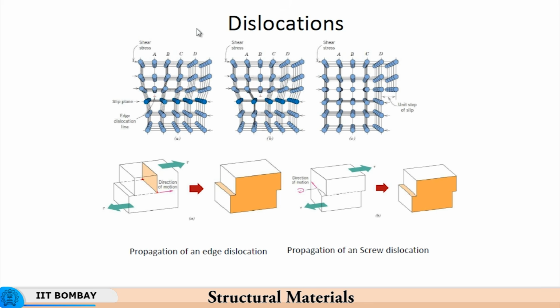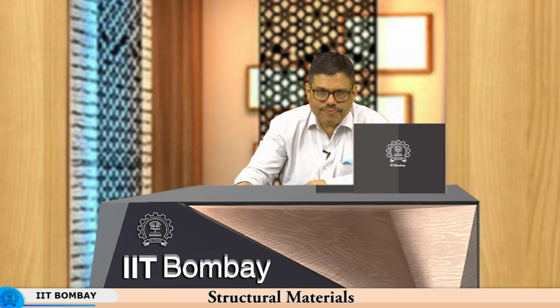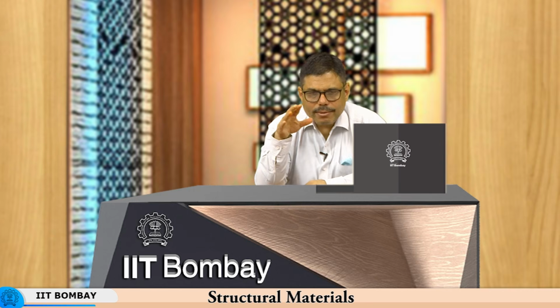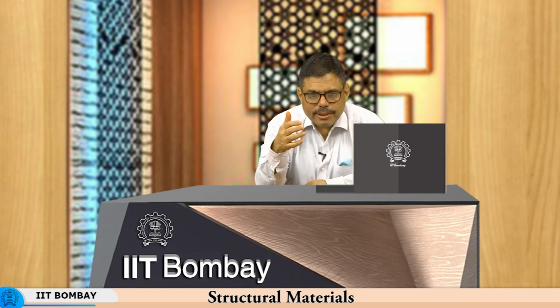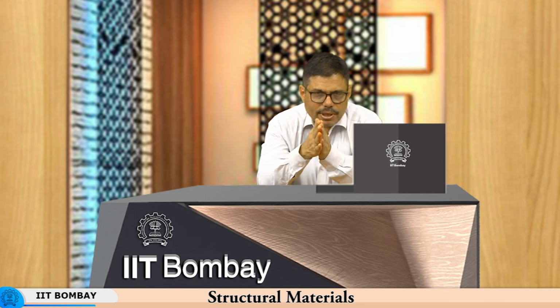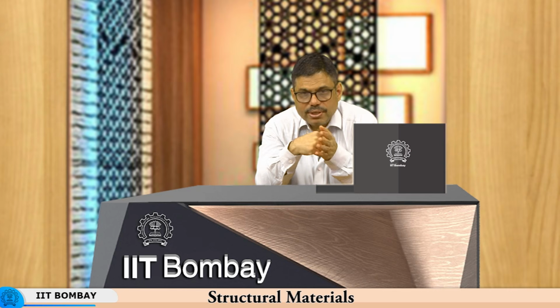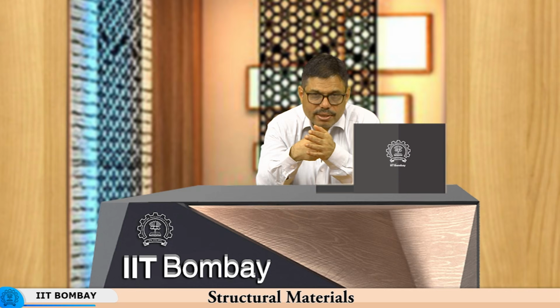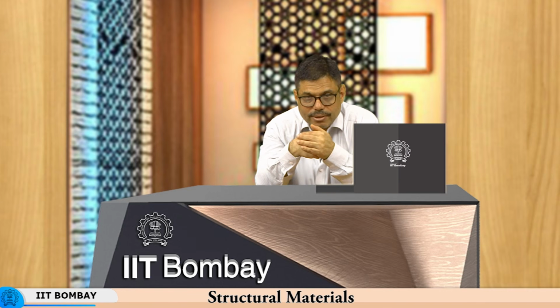So the plastic deformation or permanent deformation is something which results from dislocation movement, and that is precisely why we call dislocations defects, because if you were to really cause deformation in a defect free crystal, if the crystal were hypothetically defect free, you would need 1000 times the stress that is needed to deform that material permanently, okay, 1000 times the stress that you encounter in normal practice, right.